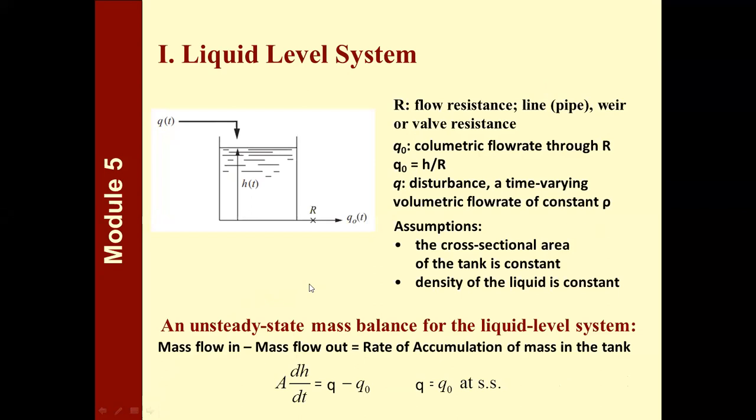So in here, we're trying to monitor changes in the level of the liquid inside the tank for changes in the volumetric inflow, or the amount of fluid that is entering our tank. So in this case, we have two very important assumptions before we go to the model differential equation. We assume that the cross-sectional area of the tank is a constant and the density of the liquid as well is constant in this case.